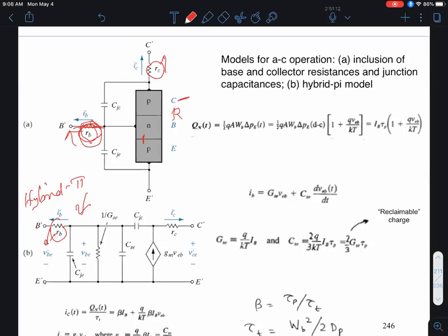And the way that's done is you make the collector doping high far away from the junction, but right next to the junction, you make it lightly doped. So that way you can have the benefit of both, because this low doping increases the breakdown voltage between the collector and the base, but farther away, if you make it highly doped, that reduces the RC, okay? It's a more complicated structure, of course, that's described in section 7.1 of the chapter that hopefully you read. And this highly doped region is sometimes called the buried collector or a sub-collector, okay? It's a slightly more complicated process to do that, all right?